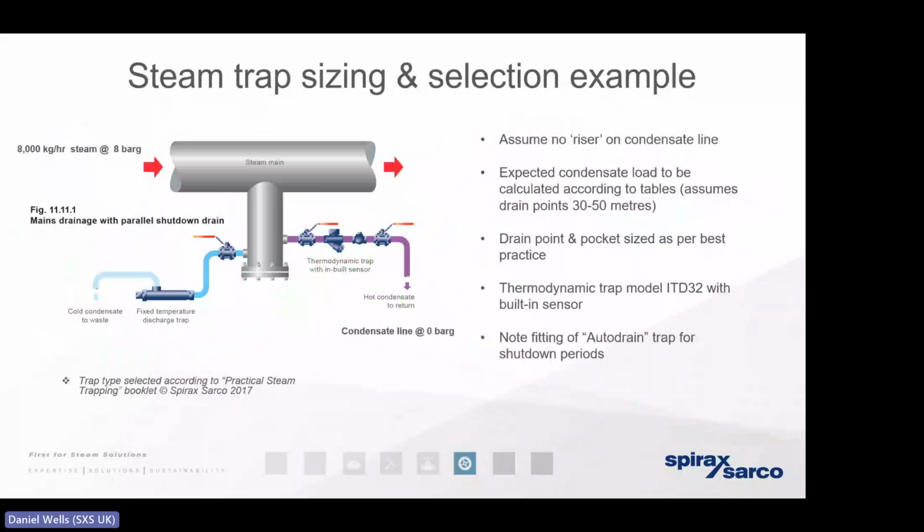They may also have a thermostatically operated trap. The benefit of having a thermostatically operated trap is that whenever we've got cold condensate in the infrastructure, where there's no steam present and no motive energy to drive that condensate away, that cold condensate can instead drain to waste, where it's not at risk of creating any mechanical damage in the infrastructure if it were to freeze or stand there for any period of time.